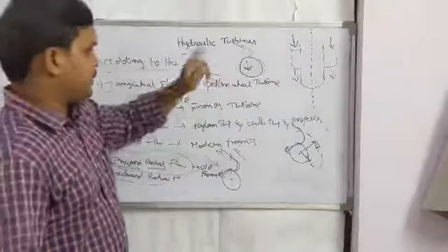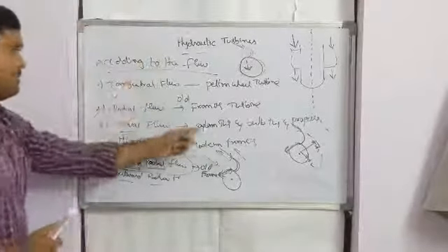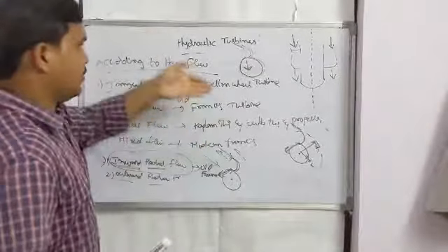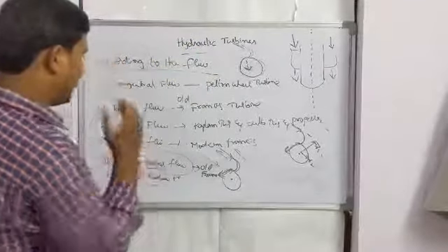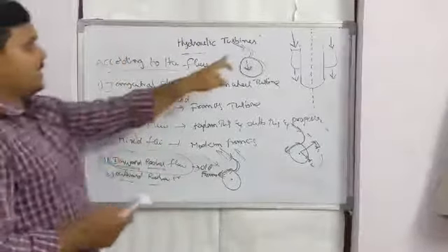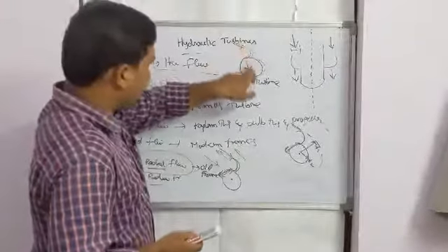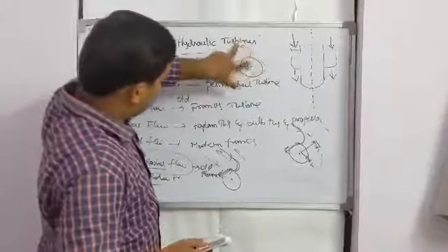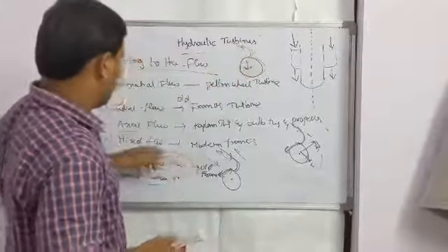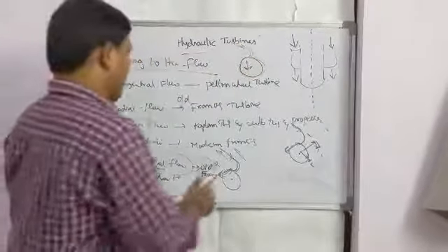Already I explained in the previous animations how the Francis turbine works. What is the direction of the inlet flow, and what is the direction of the leaving flow? The inlet to the turbine is radial and the leaving from the turbine is axial. So there is a radial and there is an axial, two types of flow, which is called mixed flow. That is the modern Francis.